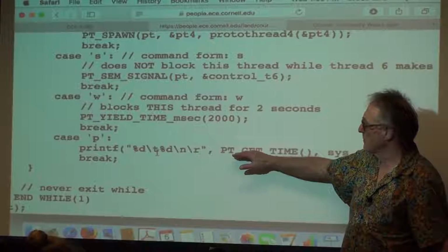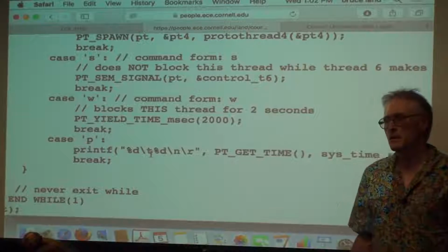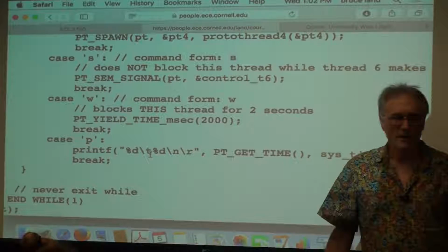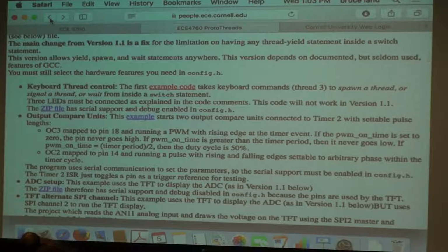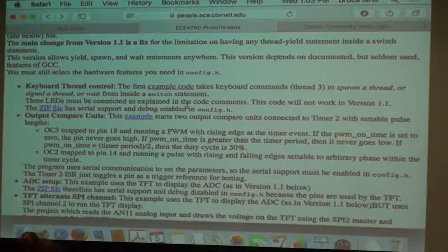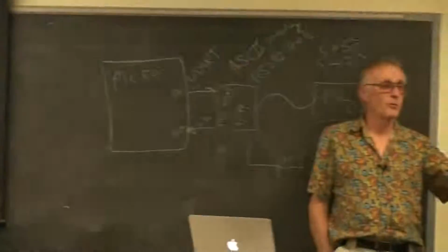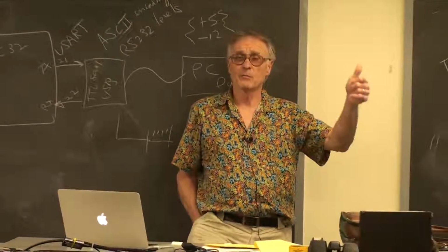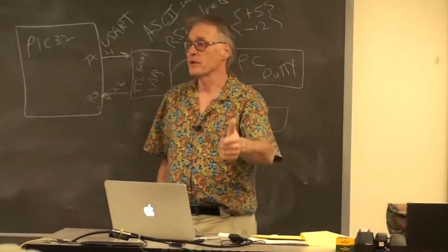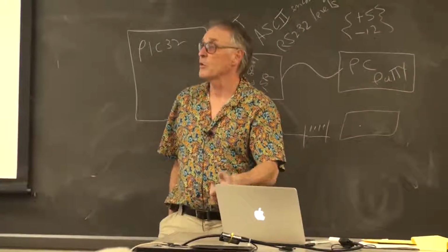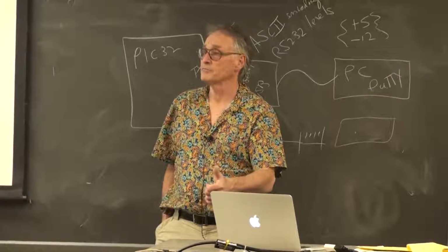My only guess is brain misfiring. So you don't want to use printf ever on your command interpreter, because it will block. For this lab, it'll block the thread which has to control the motor, and during the time the printf executes, you could have the motor over rev or under rev.